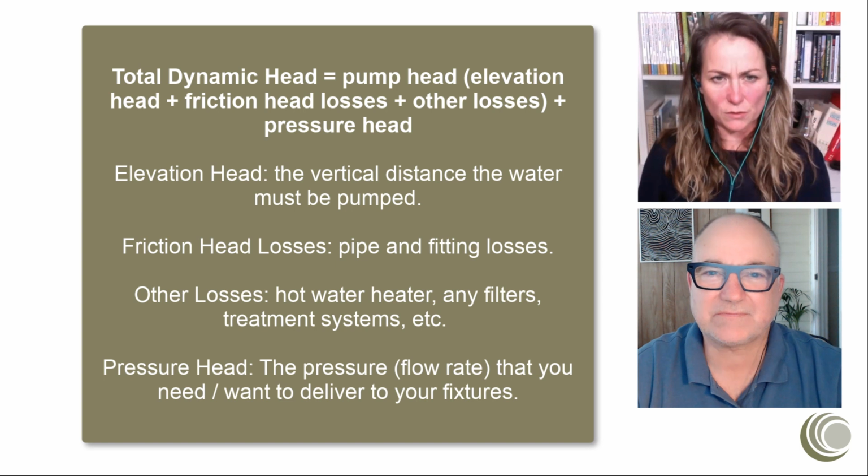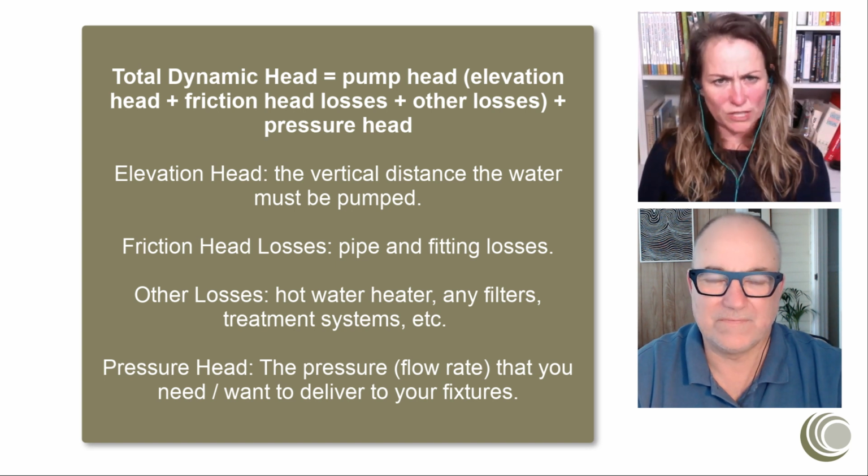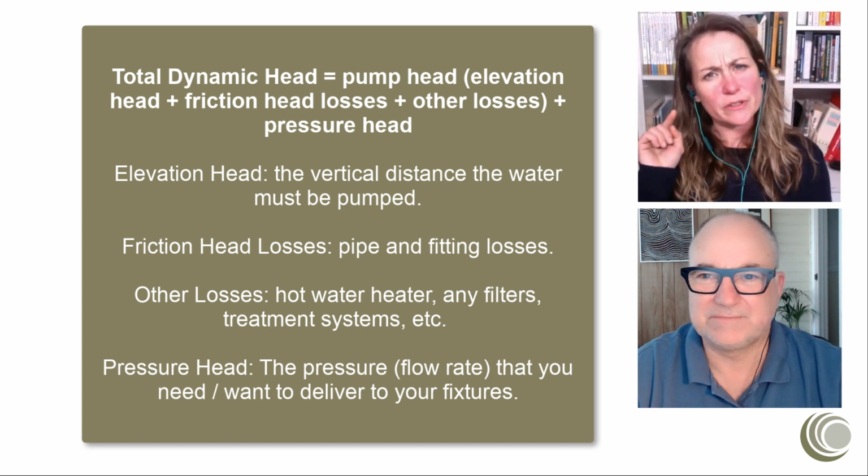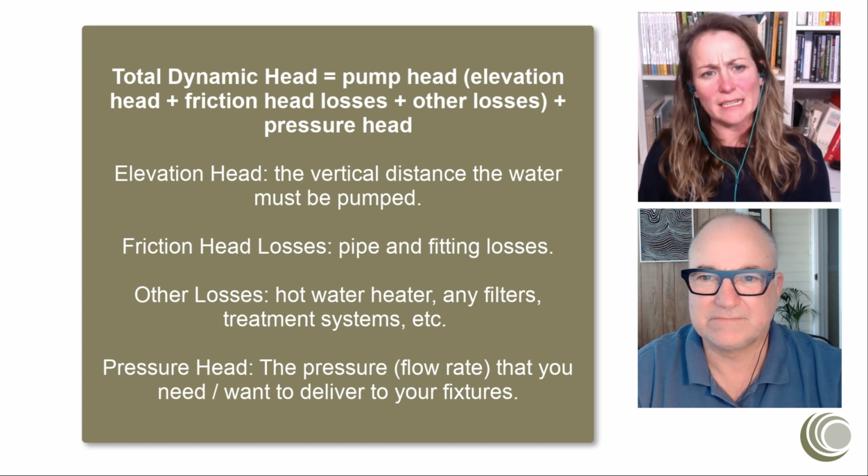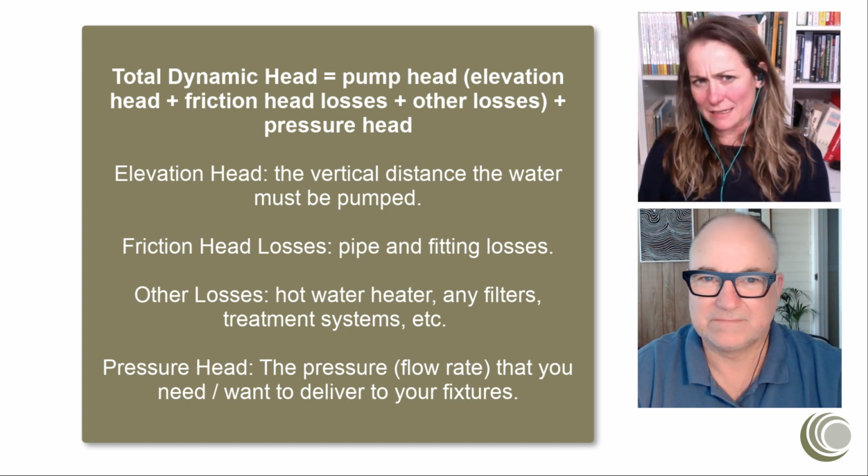You still want some residual pressure head, but earlier you implied it's surprising it doesn't actually need to be possibly quite as high as the residential codes often recommend.